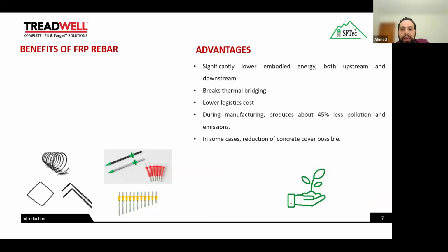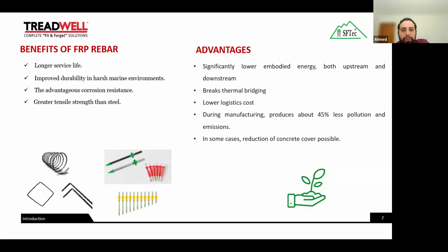First and most important, FRP bars are non-corrosive materials. This means they can significantly increase the service life of structures and expand the life cycle, especially in harsh environmental conditions. Also, FRP bars can provide high tensile strength compared to steel, much lower weight, typically about one quarter of the steel, and superior resistance to chemical exposure, and finally they are neutral to chemical, electrical and magnetic disturbances.